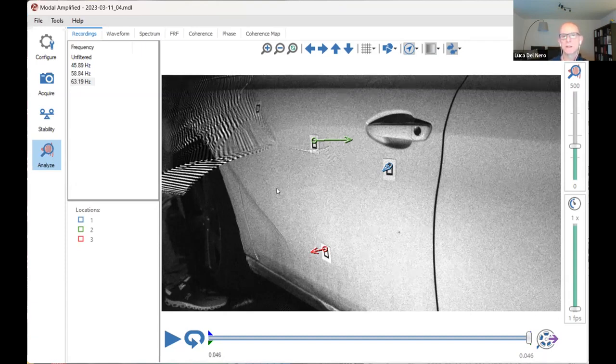In some cases, when you inspect very small parts, typically some support of a washing machine, if you stick an accelerometer on a support of a washing machine, sometimes of a pump or on a pipe, sometimes the accelerometers can be even bigger than the support itself. Today, there are very small accelerometers, but the mass of a support is in any case very small, or a coffee machine. So in this type of application, the use of an optical camera is for sure an incredible advantage.